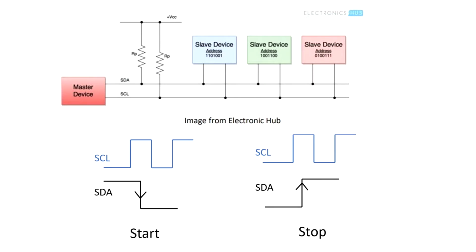The I2C is a synchronous bus made of two wires. They are connected by default to high through the resistors, as we can see in this picture. It allows multiple slave devices and also multiple masters, but only one master is going to be dominant in the communication. Each device has its own I2C address, and they all work with the same clock that's generated by the master device. We can see that one of the lines is the SDA, serial data, and the other line is the serial clock, SCL. All of the devices that are communicating through I2C are connected to those two lines.